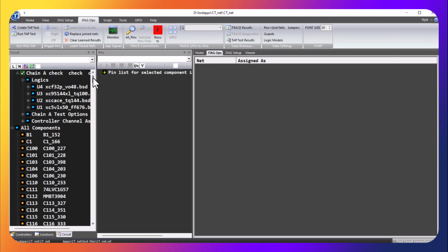And having the net list is very handy because it gives you more thorough diagnostic information, and it lets you browse through it, showing where signal activity is occurring on your board. And if you're doing a script test, it gives you access to non-script devices like memory chips and resistor networks and the like.